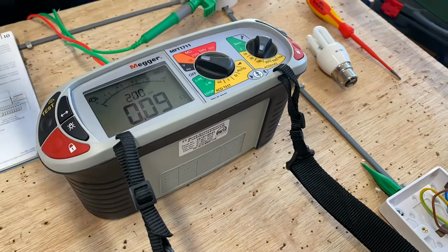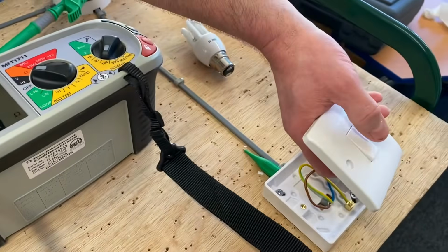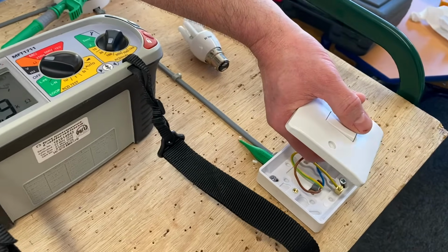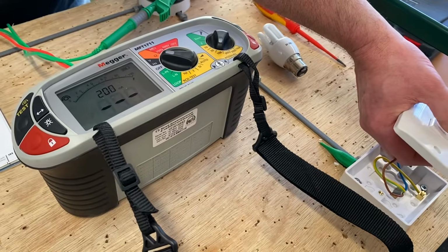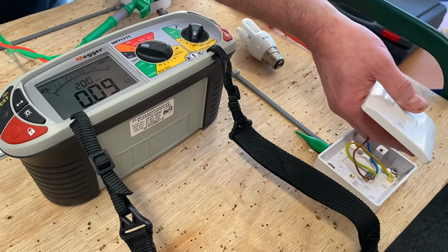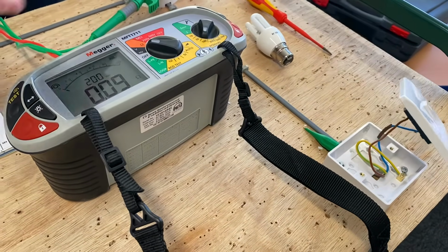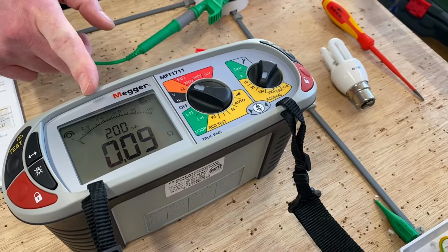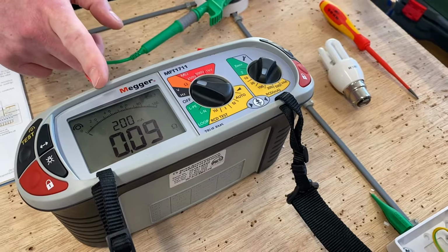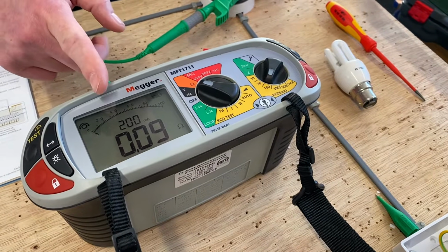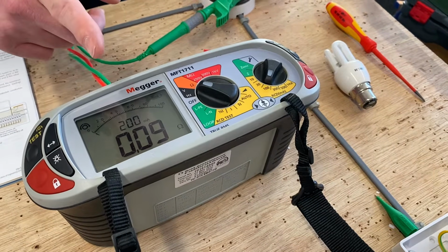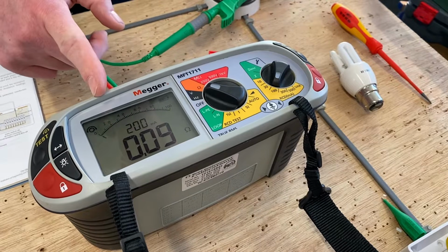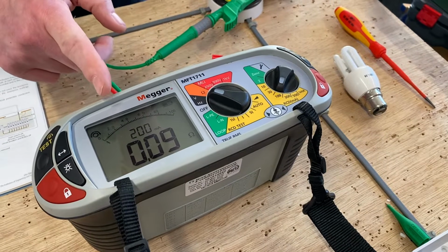So we've opened and closed that switch. So let's do that once more. So we've opened and closed that switch, and we look at the instrument deflecting, and we can prove that that switch is operational as part of our polarity check, and our readings settle down. We need to leave it in the on position for tests that are carried out in the future. We're not going to carry out them in this video, but the insulation resistance test requires all circuits to be left on, so we're going to leave it on.